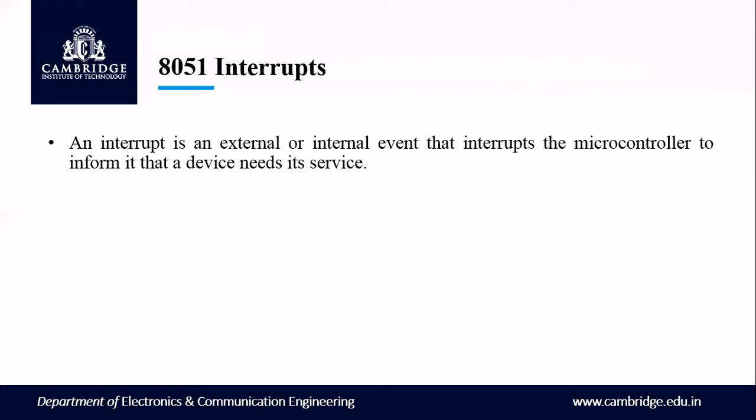So interrupt means an external peripheral device, or internally we are seeking help or a task to be done by a microcontroller. There are two types of interrupts, software interrupts and hardware interrupts. Internally, if you are writing a program and, through a program or instruction, you interrupt the microcontroller, then we call it a software interrupt. Or with a hardware interrupt, on the 8051 IC, on the pin itself, if you physically assert that particular pin, then also we can give an interrupt to the microcontroller.